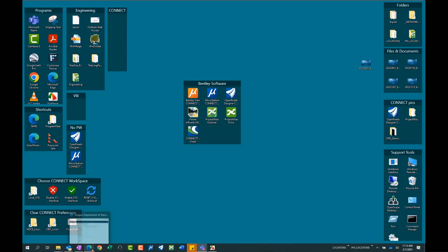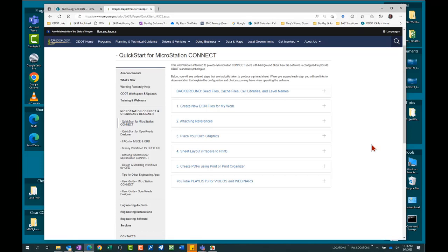The reason we can do this, provide just one piece of CAD software, is because the MicroStation program, the entire MicroStation program, is embedded within the Open Designer softwares, things like OpenRoads and OpenSite, and it's accessed from the drawing ribbon workflow. So MicroStation is the platform. It's there. It's available in all of the other pieces of software. So you really only need one piece of CAD editing software on your computer.